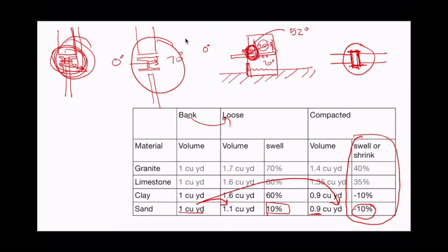And where that happens a lot is in parapets. So if we have the structure of our building in steel, and it's like this, and here's our roof in section, and inside we have, if our insulation goes through here, and then it also goes through here, you can see how if it's very cold out, our steel up here will get very cold, and maybe a little bit of the steel here will be exposed to the inside.